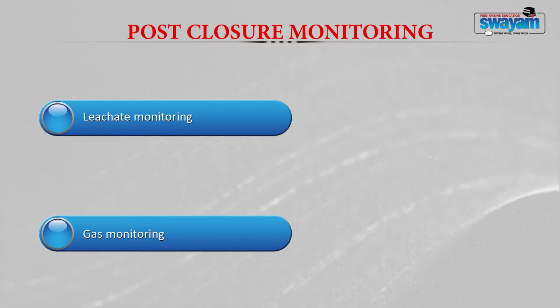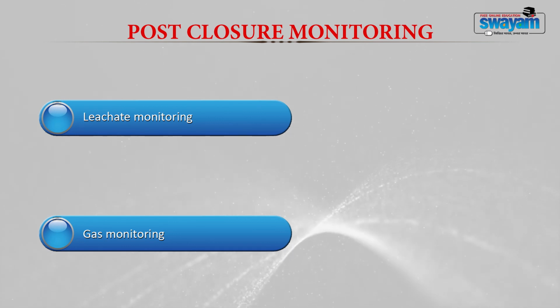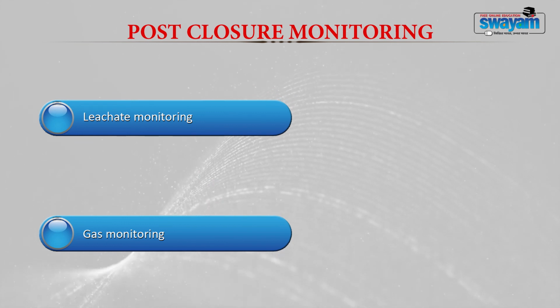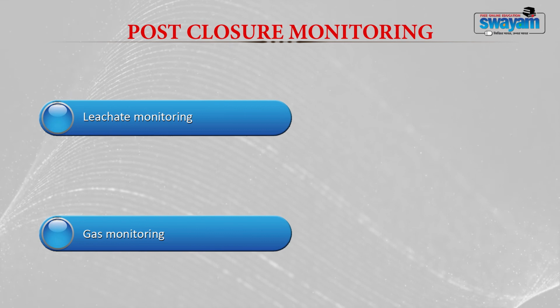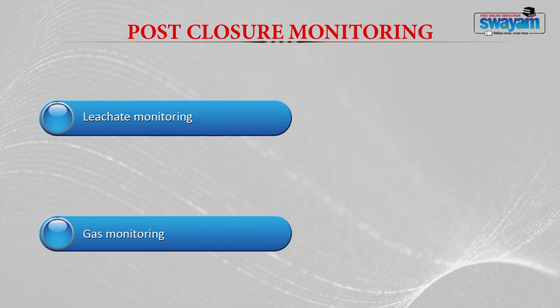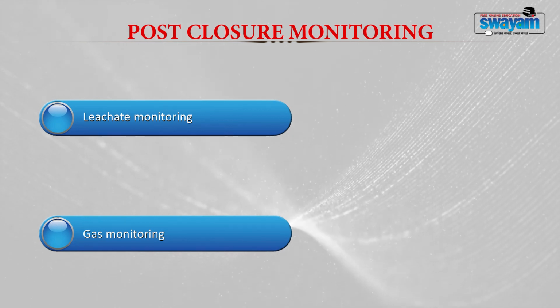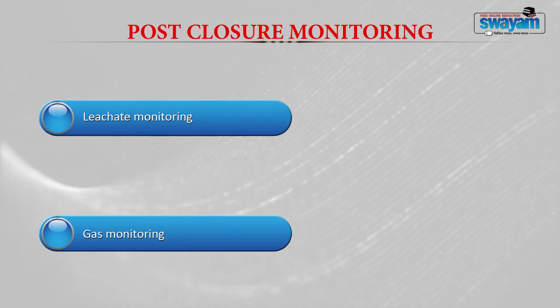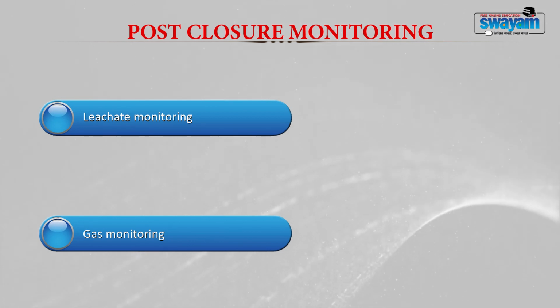Before constructing a landfill, you have reference data of water quality analysis, and afterwards you can measure and compare the water quality with the reference. You can see whether there is any leakage, breakage or rupture in your liner material, and whether the leachate is entering or contaminating your groundwater or not. Then for gas monitoring, you should have a gas monitoring station to find out if there is any excess leakage of gas from the landfill cover.